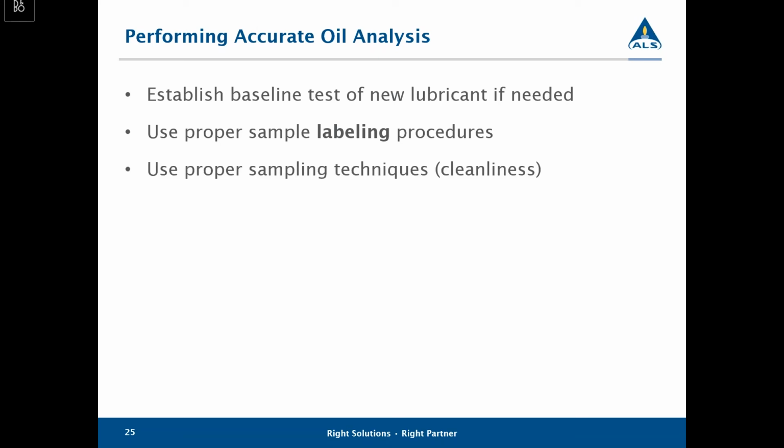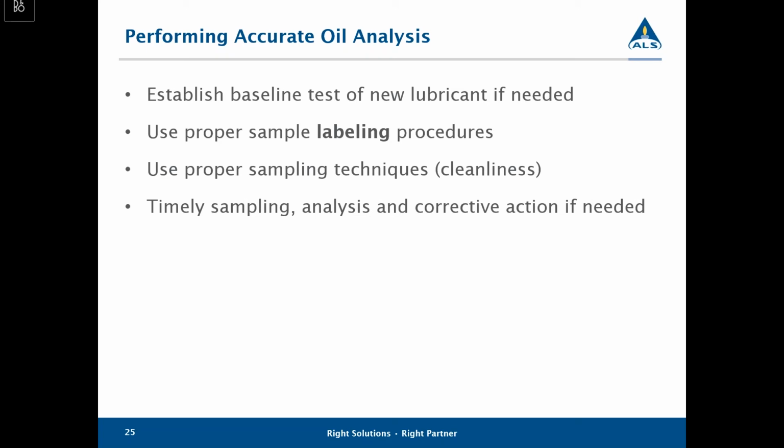Sampling techniques is very important. As I discussed, timely sampling is huge. I have received a few calls where somebody has asked me, hey, if the oil has sat for 3 months, can you still test it? And yes, we can, but the concern is have you flown that aircraft in the past 3 months? And if you have, what value are you going to gain from testing that?